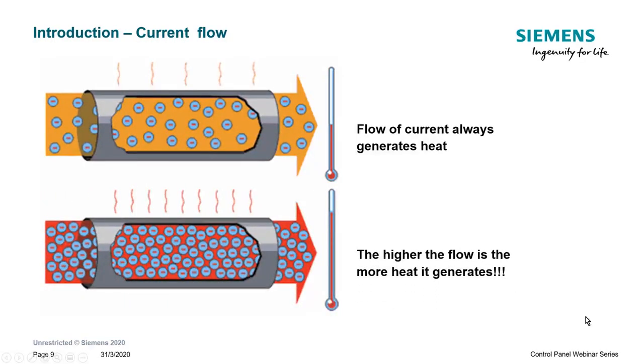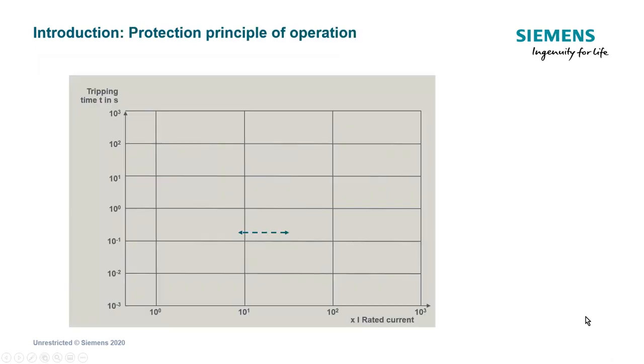But when we work at a higher current, above this rated current, it creates more heat. Now the device cannot dissipate the heat to the outside as easily, meaning the temperature inside of it rises. And when we do not process these overload currents, well, we will have the issue of the short circuit currents.